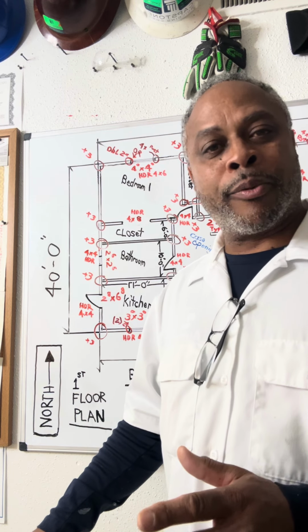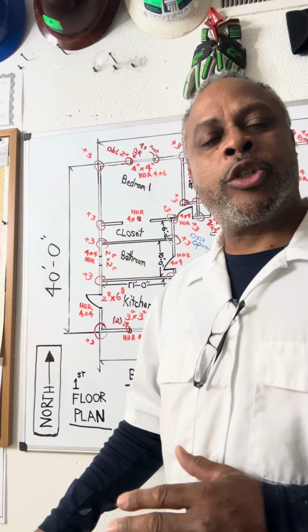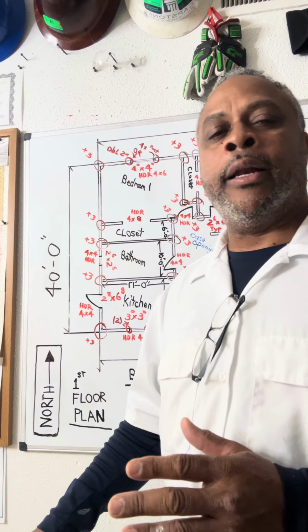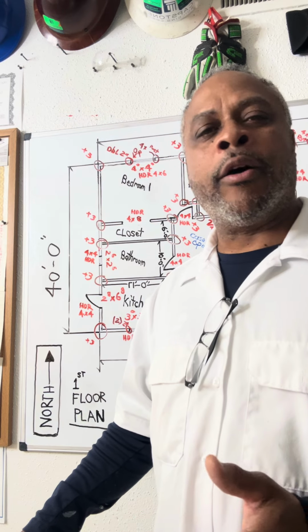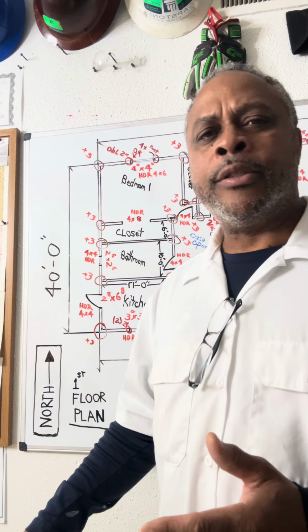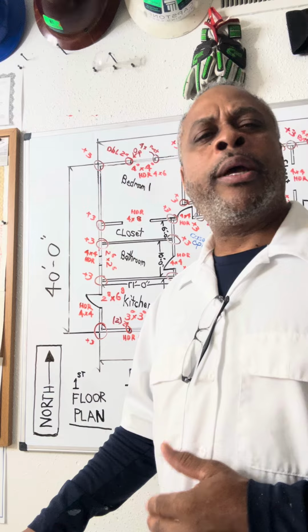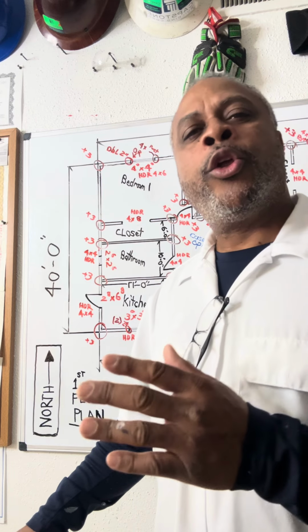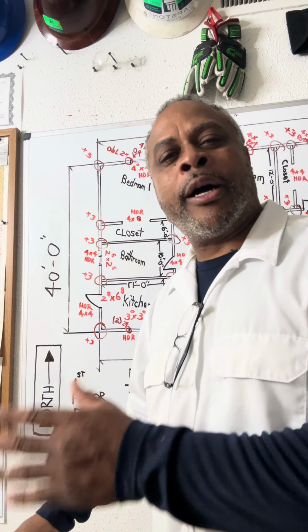And always remember, separate your lumber so you know where it's at. And watch your lumber. And don't let your carpenters just run through your lumber, because there are a lot of unskilled carpenters out there. And they'll pick up a 16-footer and cut 4 feet off of it. Why? Don't let nobody do that, because that 16-footer could have been plate material. And this guy is cutting 4 foot off of that. Direct your guys, or direct the crew, what lumber to cut from.